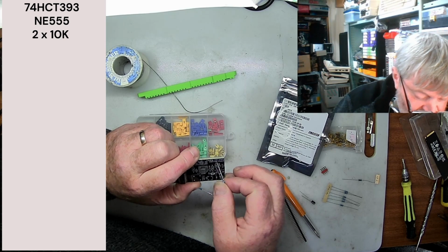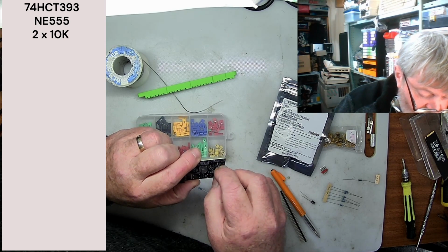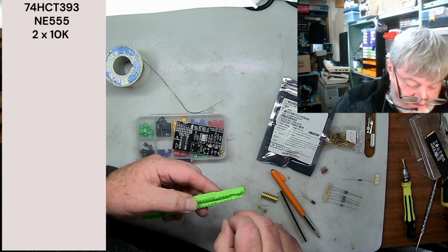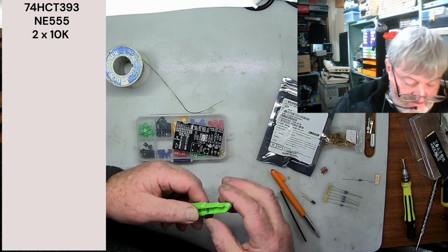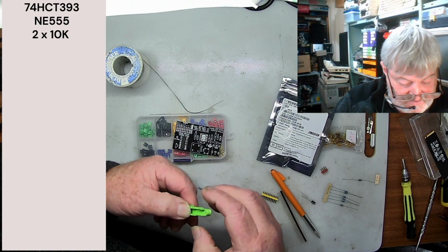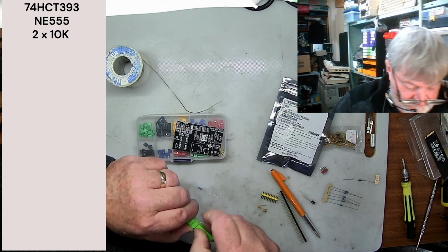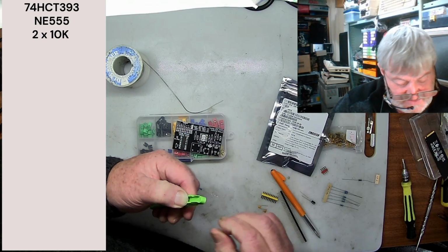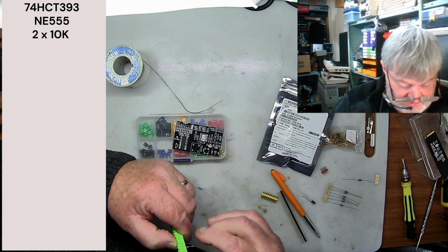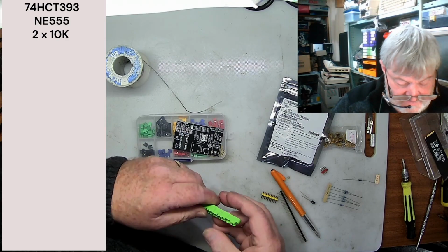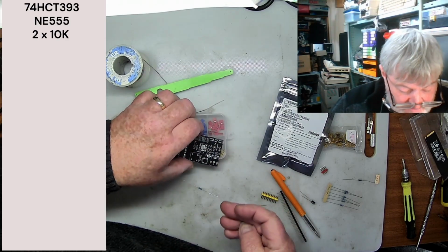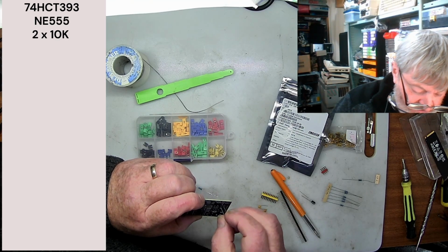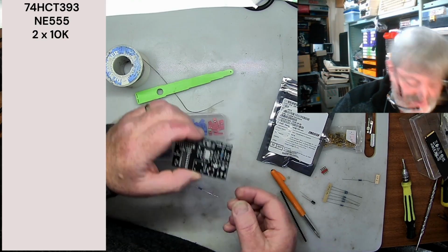Now I think this is the right size. If it's not, we just need to go to the next one down. Yeah, it's a little bit wide, so we need to step down to the next one, so that's cool. So we can go into the next one, put it on there, and then we can just rebend our legs. These are fairly soft metal, so they do bend quite easily. So just bend those down and pop that out. You don't have to worry about doing this. You can always just hand bend them and put them in, but if you want something which looks a bit neater, that's an easy way to do it.